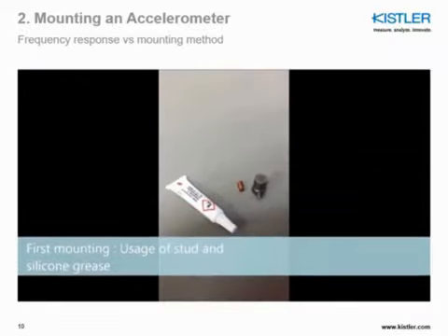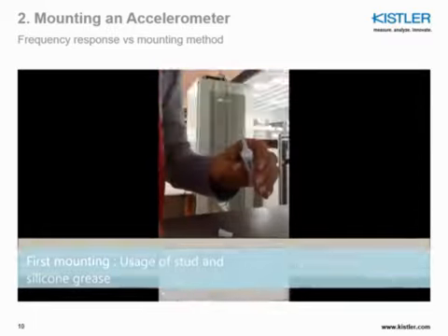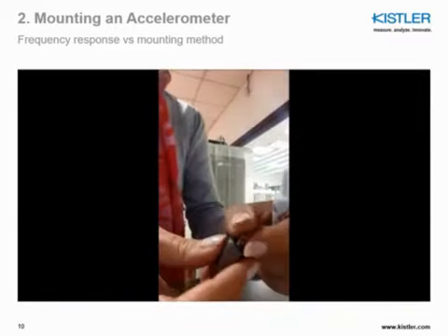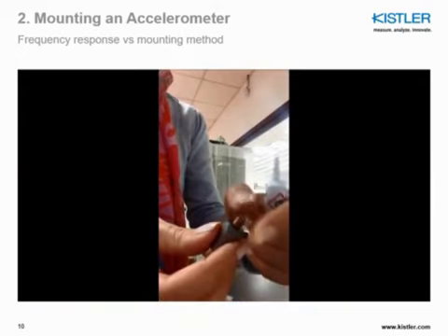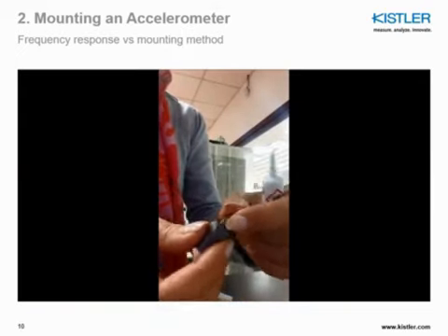First, we will mount the sensor using grease and a stud. So we will screw down the stud and then apply the grease.